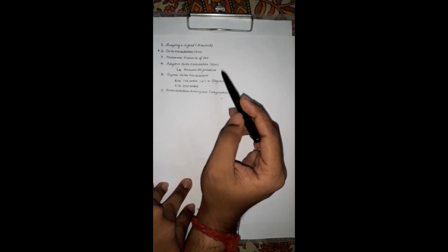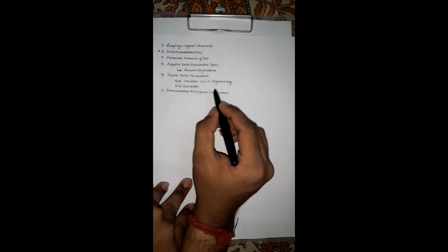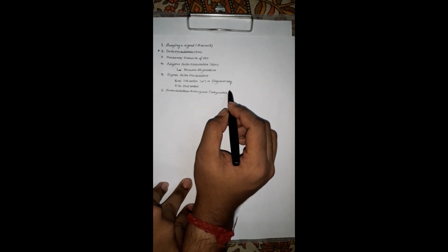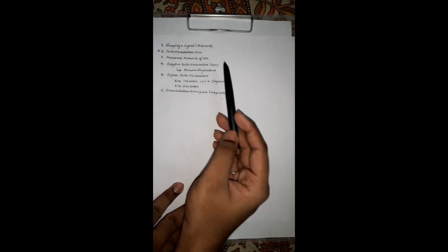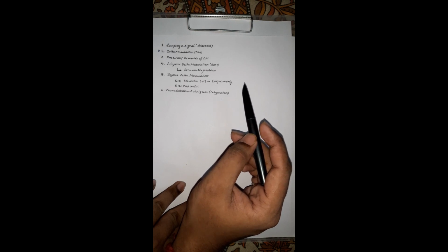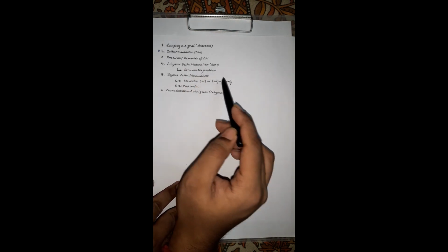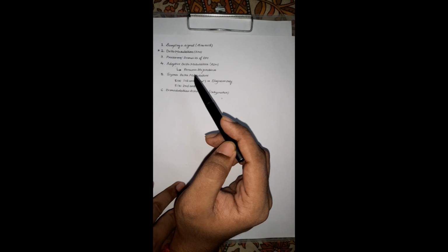The demodulation technique for delta modulation, adaptive delta modulation as well as sigma delta modulation is the same. Just a single integrator is used in the demodulator circuitry. Why this single integrator is used, I will tell you, and I will prove that by using the integrator we mathematically get the same sinusoidal signal that we have transmitted. Okay. And one more interesting thing that most people may be confused about: all these three modulation techniques that I am going to discuss here are digital modulation techniques.